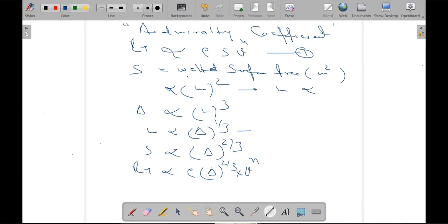Now I'm just drawing a straight line here just to separate the two areas. Rho can be assumed to be constant for seawater, approximately 1.025. Now if you see here, we still have to define n. N is the index which depends upon the speed of the vessel, and n is equal to 2 for slow speed vessels. Slow speed vessels, all our marine vessels are slow speed.